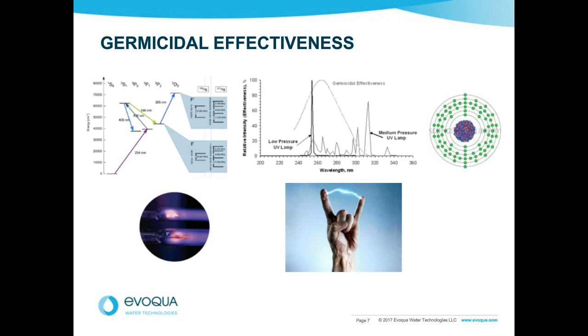Here in the US, we have different doses. We have to verify the dose algorithm rather than validate to a certain number. So it gives us much more flexibility in application. Yes, it's true that the European validation protocols are more energy consumptive because there's more to impede the passage of light from the lamp through the quartz into the water.